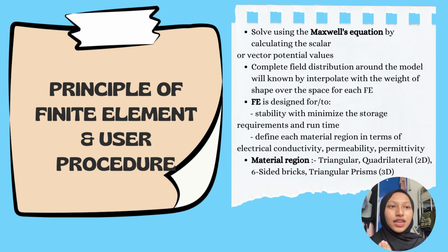So this FE, which is finite element software, is designed for solution stability with minimization of the storage requirements and runtime, and also to define each material region in terms of its electrical conductivity, permeability and permittivity.